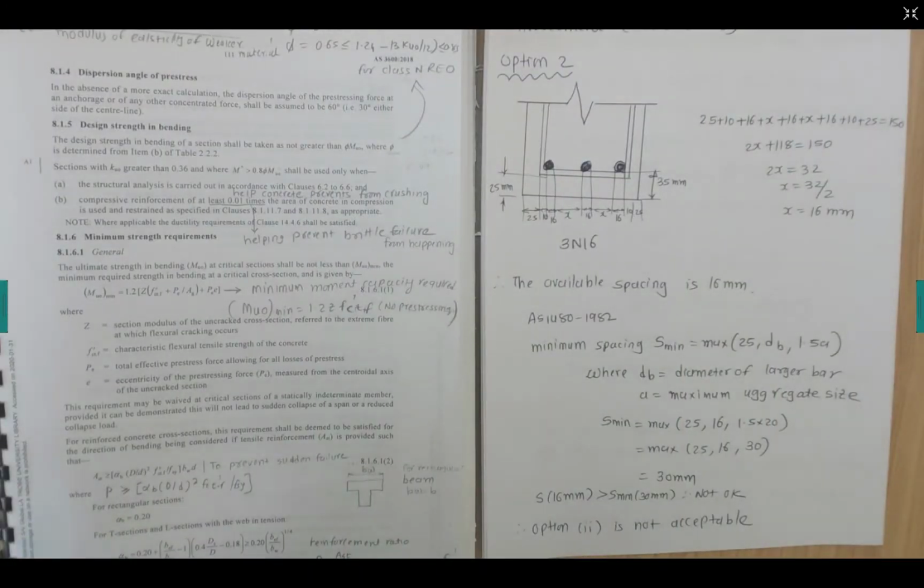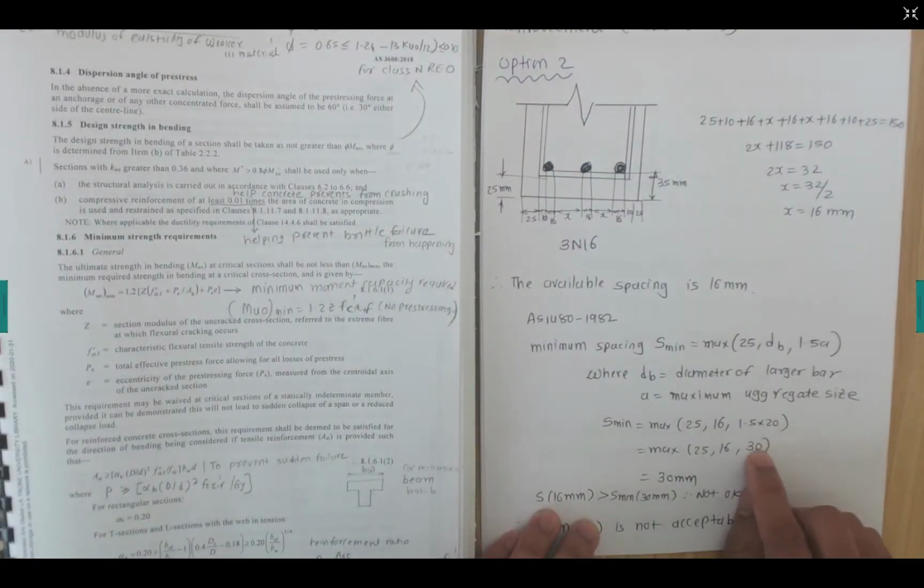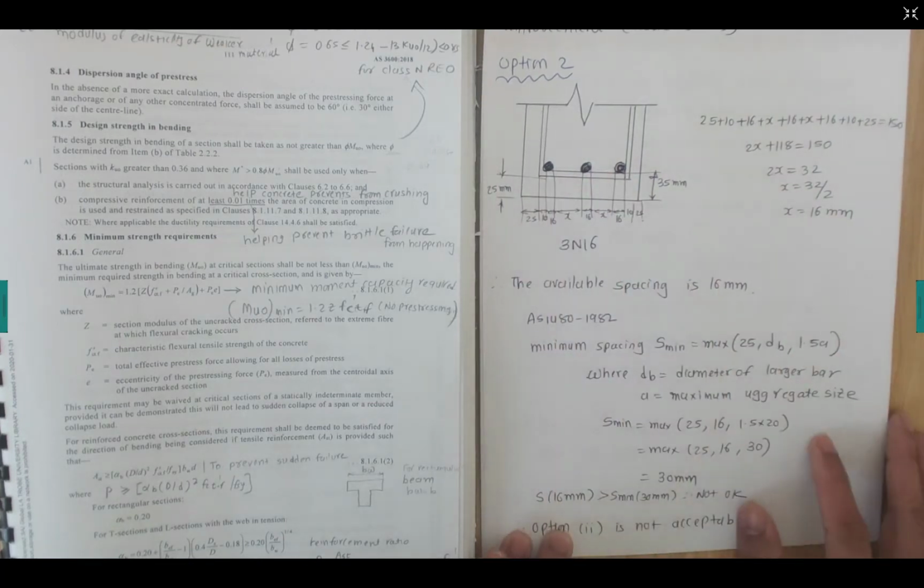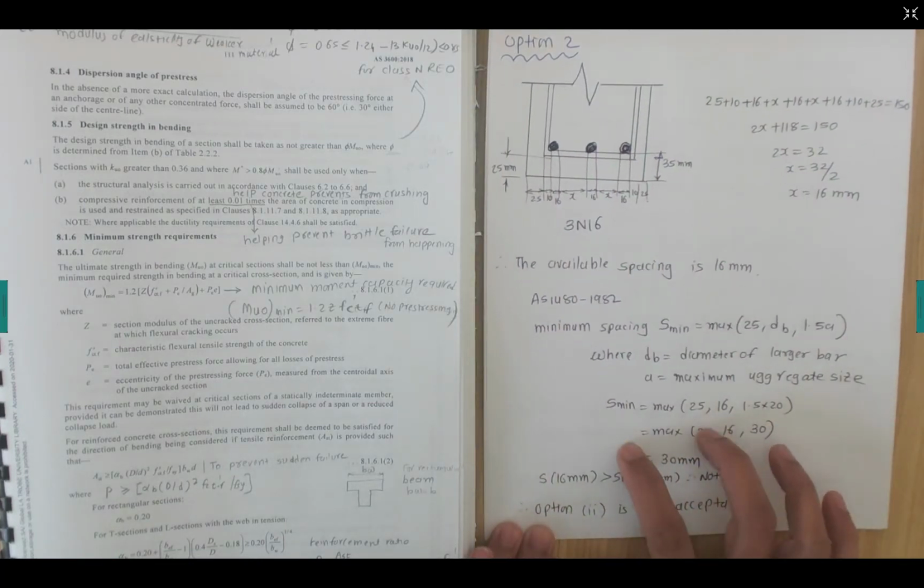So we put these 20 millimeters here, and that gives 30. So if I take the maximum value, 30 millimeters is the minimum gap that we should provide. That is just a guide for us to have a reference value. As I mentioned, AS3600 does not recommend a value, but at least we need some guide for this example. Therefore I just have 30 millimeters by this reference.